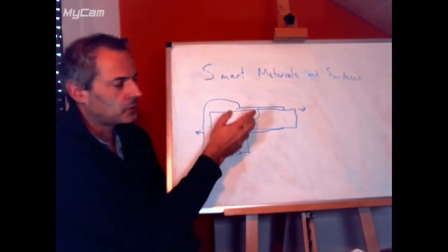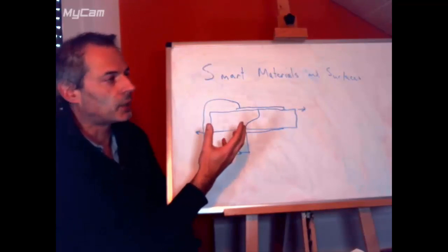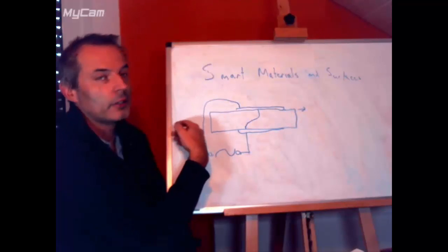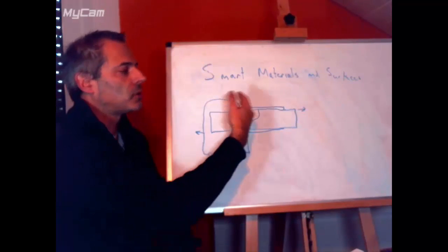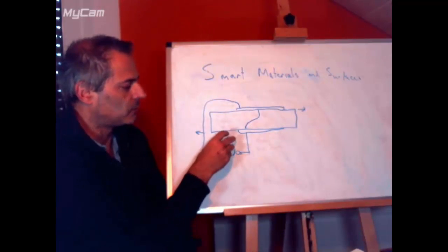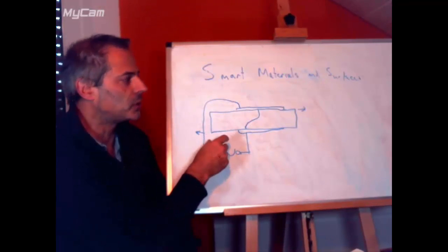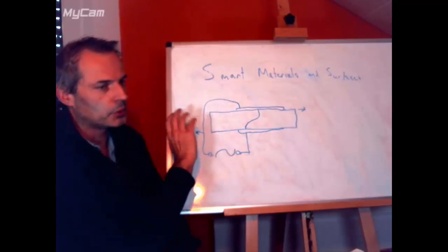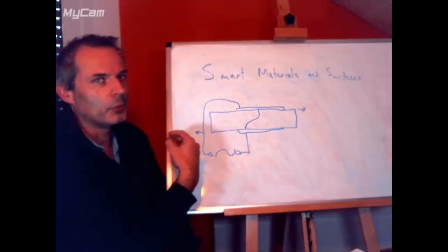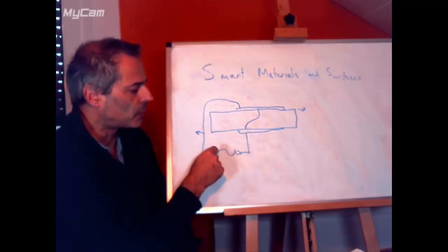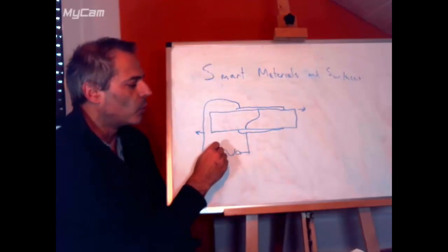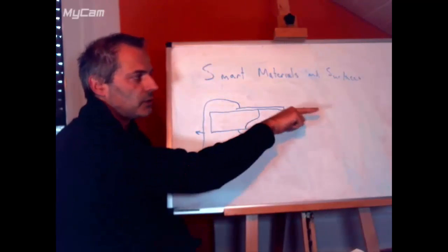If the quartz oscillates at this frequency, it will be able to couple particularly well with the field, because when it's moving back of its own accord, because it's oscillating back, we will be powering it as well. The AC will have switched to the right direction to be pushing it. If we're close to it but not quite, then we'll have a problem, because if our AC is slower, then it will start to come back while we're still pushing it in this direction.